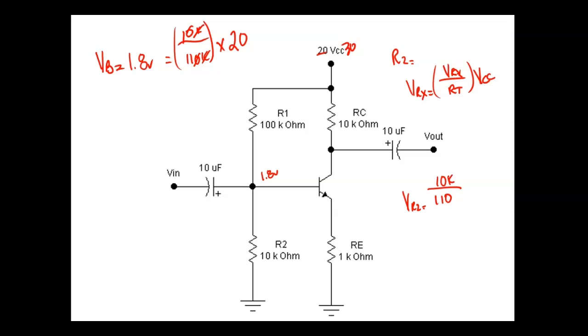That's what's nice about the voltage divider formula, especially on these. Most of the time, you can come up with RT without even picking up a calculator. And this is K also. Well, what do I know? If it's on the top and the bottom, they can cancel out, right? So that marks out the K, that marks out that 0. So I know R2 is going to drop 1/11 of the voltage before I pick up a calculator. 1/10 would be 2 volts, but 1/11 is going to be slightly less. Times 20.